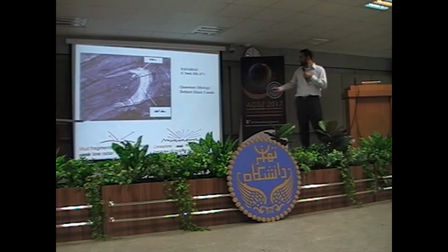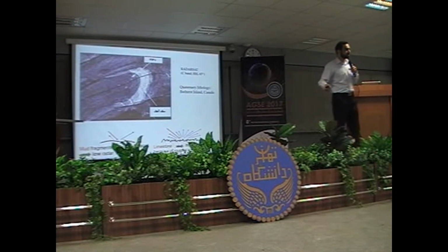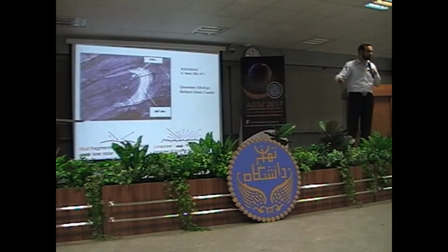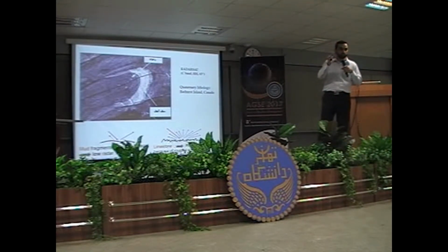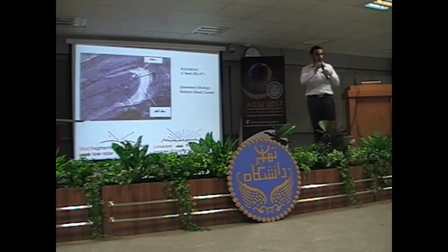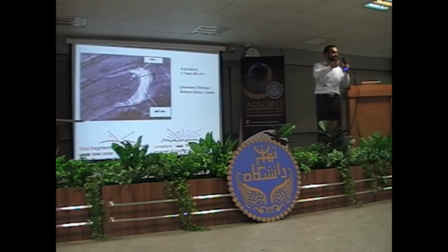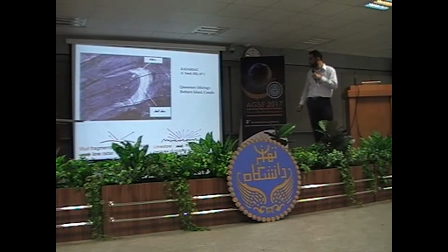But this is usually not the case in optical remote sensing. Optical remote sensing is not sensitive to the roughness, because the wavelengths are a few microns, and a few microns are not enough to see the roughness. Whereas 3 centimeters, 5 centimeters, 20 centimeters, and 1 meter wavelengths are quite enough to be sensitive to the roughness of an area.